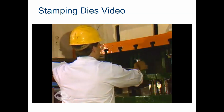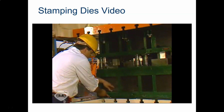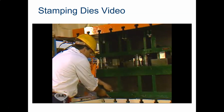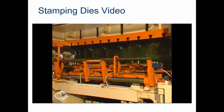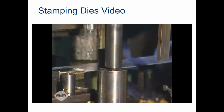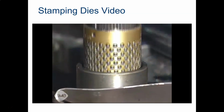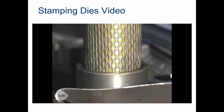The upper half of the die set is clamped to the press ram, while the lower half is secured to the bolster plate on the press bed. The die halves are opened and closed by movement of the press ram. Guide pins sliding in matched bushings or ball bearing bushings align the upper and lower half of the die set.